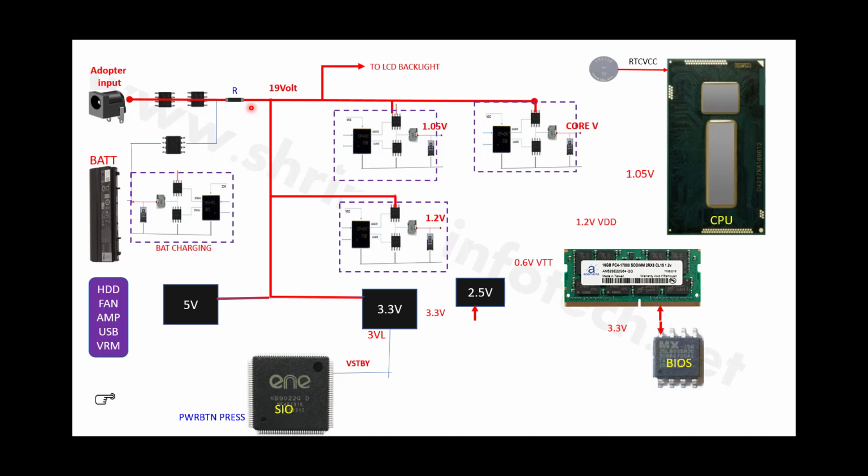If it is a ceramic capacitor, simply remove the capacitor, no need to put any back. If you put another capacitor, that is okay, but if you don't put any other ceramic capacitor, it doesn't matter, because there are varieties of ceramic capacitors there. But if the short is in some MOSFET or chip or some polarized capacitor, in that case you have to replace that particular component. So we'll see everything practically.